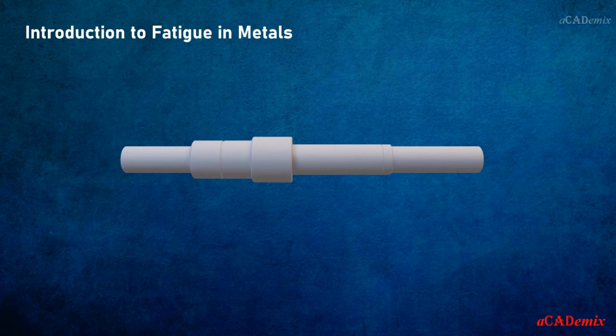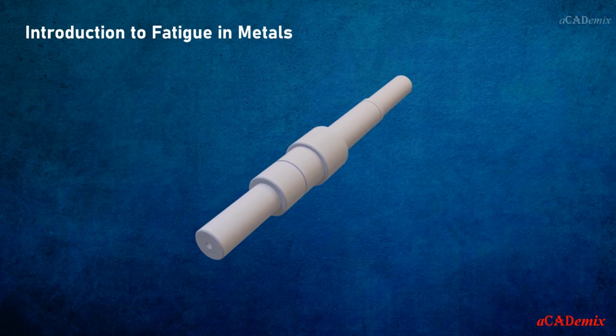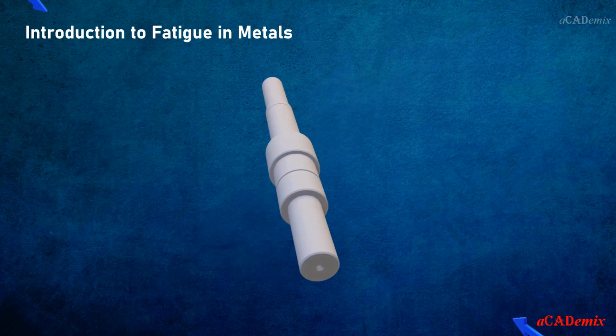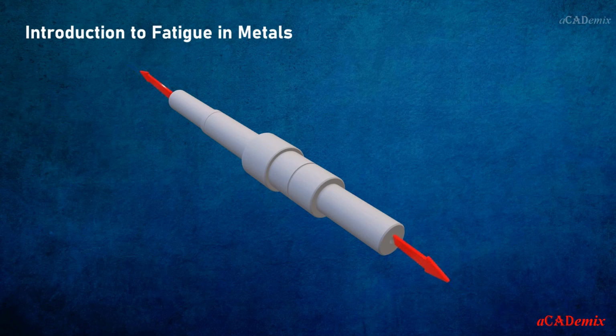For example, consider a small fiber on the surface of a rotating shaft which is subjected to bending loads. This shaft may undergo a tensile load or a compressive load or a combination of both. Let's say the shaft undergoes both tension and compression for each revolution of the shaft. If the shaft is rotating at 1800 rpm, the fiber may be stressed in tension and compression 1800 times each minute. The stress induced on the fiber is called alternating or fluctuating stress, and the condition is called dynamic condition.